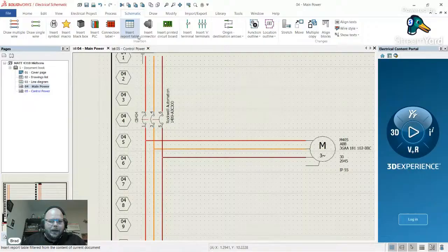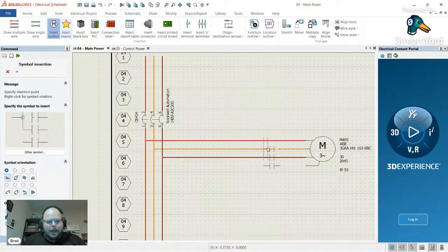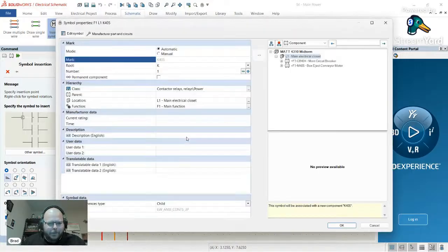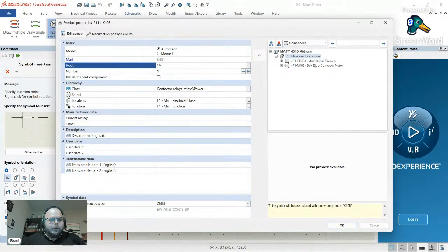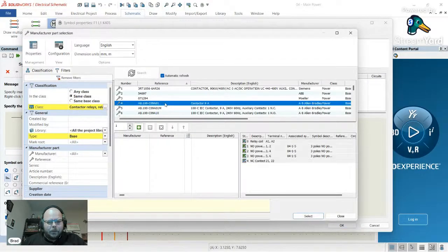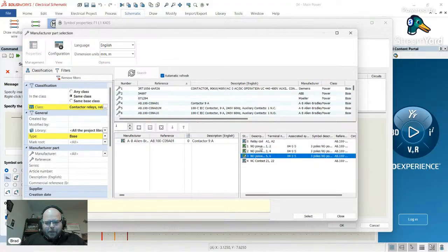a better option. Now, again, for a full design, I would go through and figure out how much that motor draws, yada, yada. But again, CR control relay, I should change that in my base setup. And then that C09 contactor, 9 amps. Now, I'm green. Let's add it. I'm green on three because they do match the symbol. That's why these are green. They're normally open power contacts.